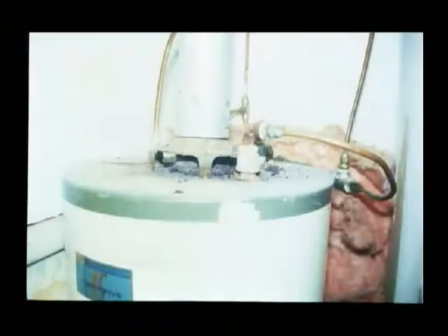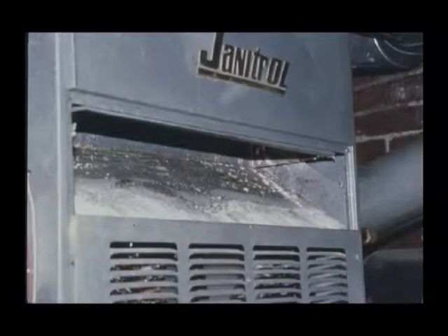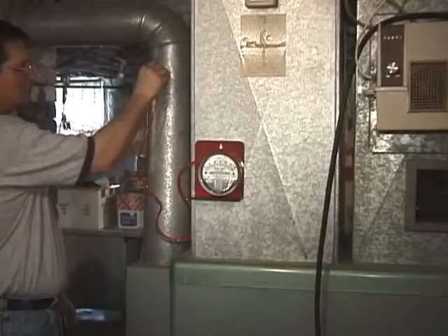By and large, Category 3 and 4 appliances are much less susceptible to many of the venting problems Category 1 appliances often experience. Many Category 3 and 4 appliances are also sealed two-pipe systems that are not affected by negative pressures in the house. For all these reasons, it is normally not required to test the draft on Category 3 and 4 systems. Also for these reasons, as a general rule, Comfort Institute recommends sealed combustion Category 3 or 4 equipment use over Category 1 systems. Increased safety is in fact a greater benefit than the lower utility costs.